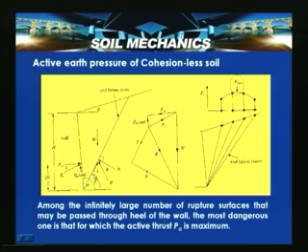We need to find out the surface which actually gives the maximum active thrust. Initially we do not know this particular surface, so we need to take innumerable surfaces. Otherwise, for maximum PA, we can differentiate this expression which we derived in the previous slide with respect to theta, get the angle theta, and from there we can calculate what is PA.